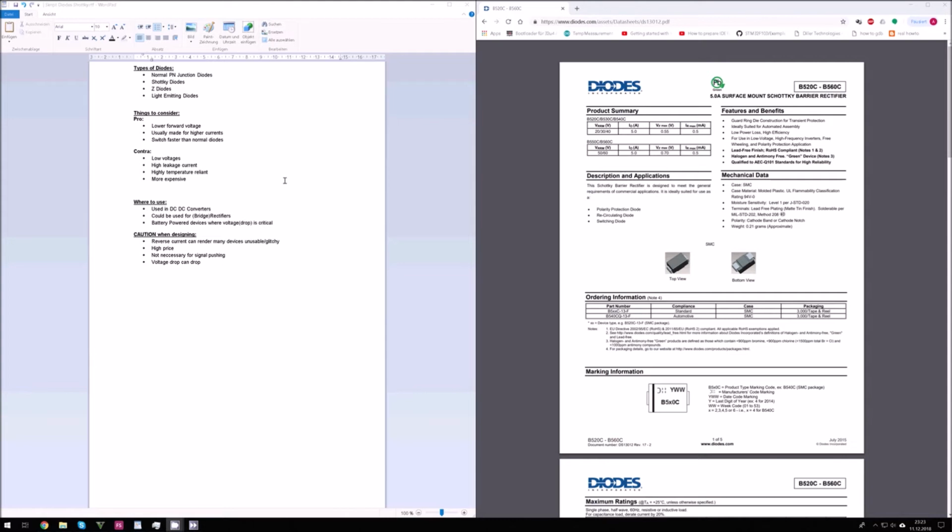This means that the diode is not perfect. To tell you first off, no diode is perfect. Diodes are used to make current only go into one direction, but no diode can really do that perfectly. We always have a certain reverse current. With normal NP or PN junction diodes, this reverse current can be as low as a few nanoamps. But with Schottky diodes, it always is at a few microamps, if not milliamps.